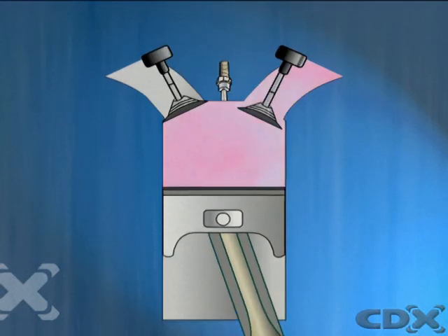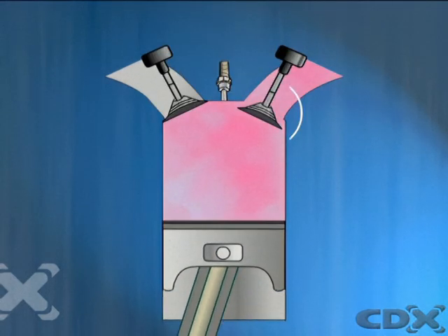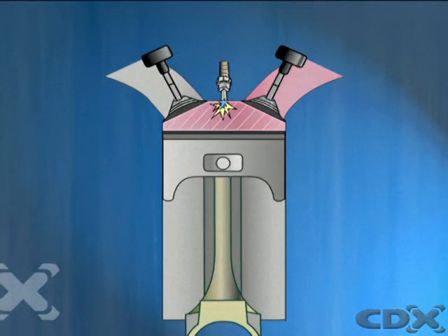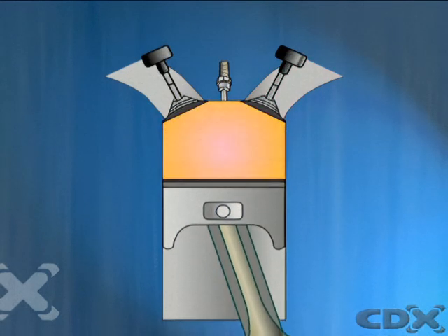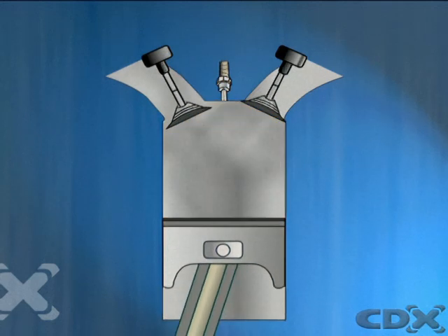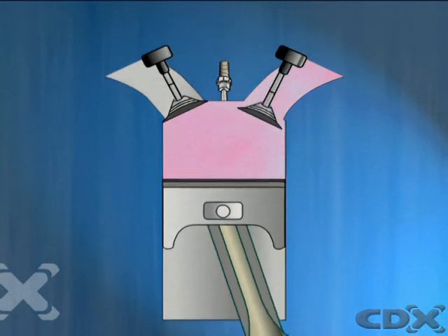The effective compression stroke is shortened by delaying the closing time of the intake valve at the beginning of the compression stroke. The combustion chamber is smaller than that of a conventional engine, so the compression pressure at ignition is still typically the same as that of a conventional four-stroke engine.